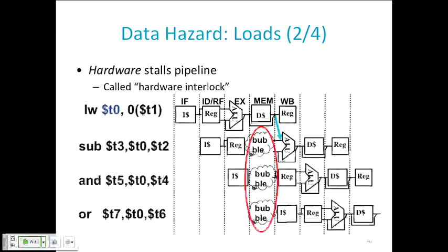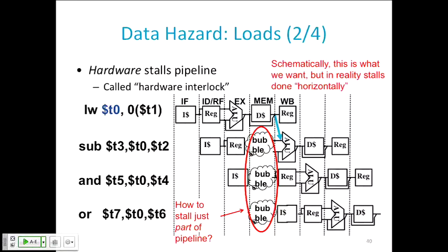Right, so then this is showing the actual bypassing path from the output of the memory to the input of the ALU. Right? Now one issue here is how does this stall actually happen? Well, this is what you draw sometimes, but the way it really happens is